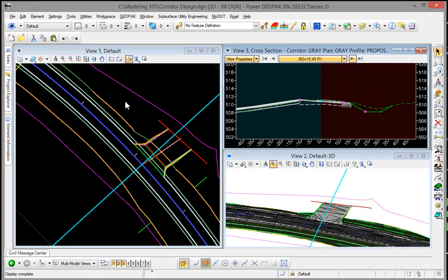But if I'm coming in and adding key stations in my design view, or targeting my edge of pavement with parametric constraints or point controls, I don't necessarily need my model, my dynamic sections and my profile view open, so I may close those, and that will help optimize things as well. Just remember that these dynamic views require additional processing to show those views active in real time, so there's nothing wrong with having them open. Again, it's just another tip on things to consider, especially when you have very large projects, several miles long.